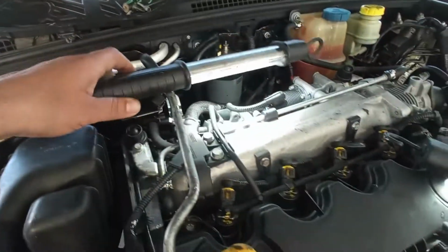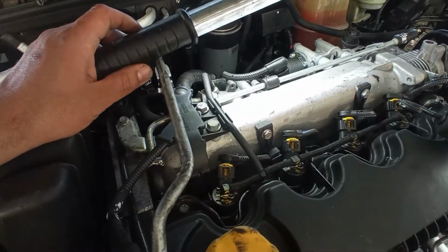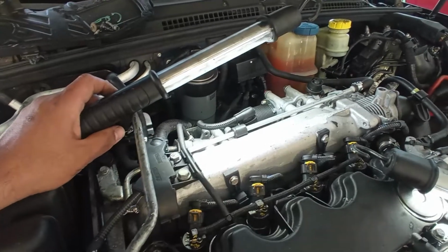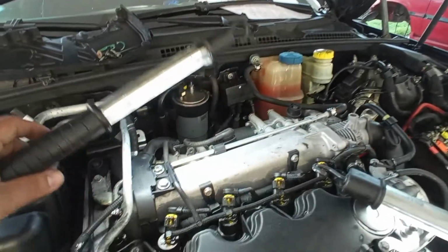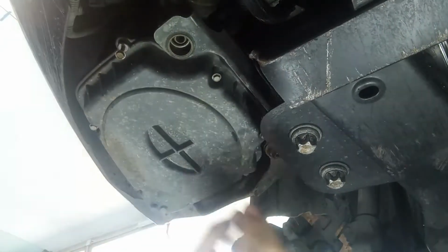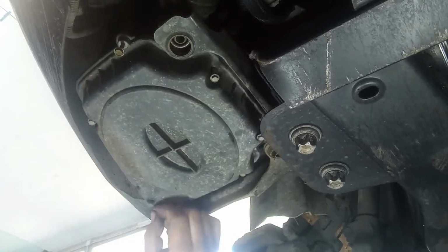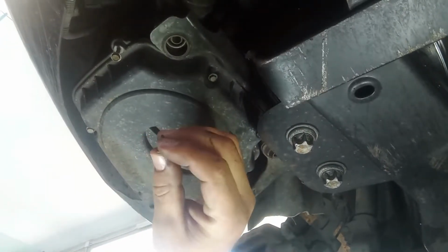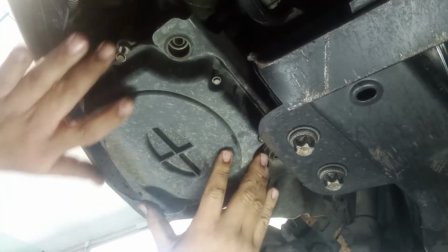I can also do here something on the MAP sensor, because as you could see on other videos, that also gets a little bit dirty, and just by maintenance I like to clean it. So taking here the 7mm head bolts, 1, 2, 3, 4, 5, 6, 7. I will remove here the box for this thing over here. I already did a short for this. You can follow that if you want to. Let's remove the cover and see what we find.